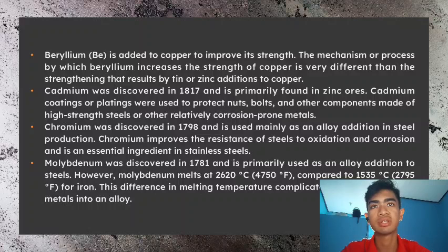Corrosion would severely limit the utility of steels if chromium were not added. Stainless steel contains up to 30% chromium, and although the primary function of chromium additions is to improve corrosion or chemical behavior, chromium in small quantities also improves the strength of alloy steel.